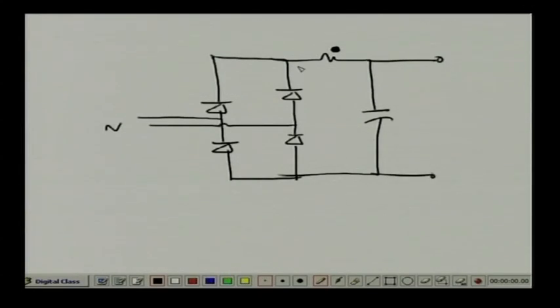These are typical circuits also used in SMPS, the switch mode power supply, for giving power to all the chips. Even though there is a switch mode supply, for that reason they use a small series regulator. In those series regulators, I have a big diode rectifier like this one, and it will utilize the thermistor. Thermistor is also used in electronic circuits for stabilization. The Q point stability is very important in the devices. Once you switch on, especially in a circuit where there is a feedback, there is a chance of oscillation.